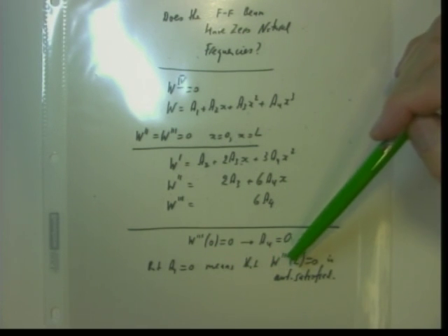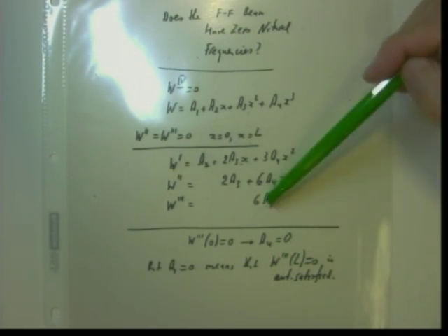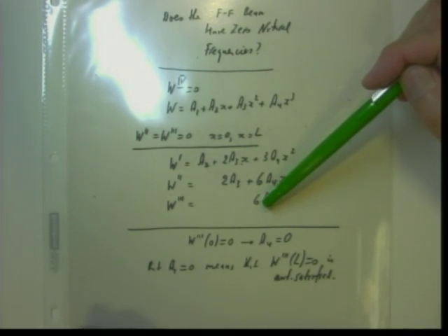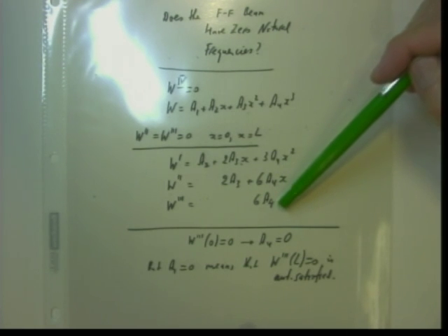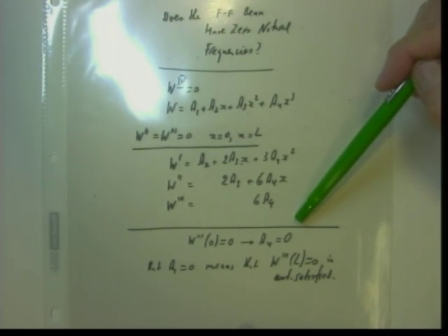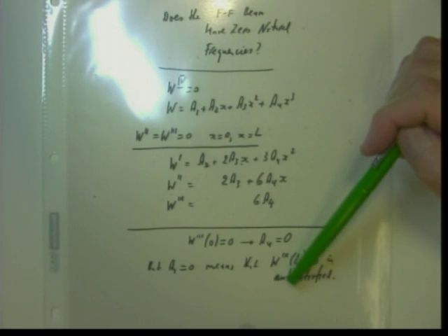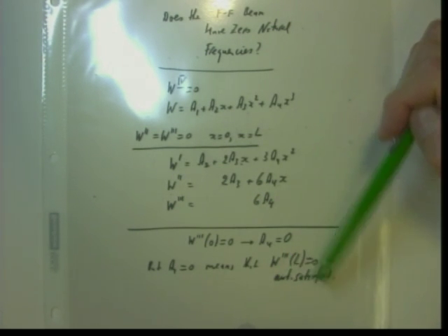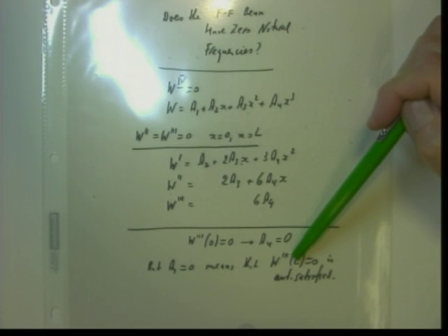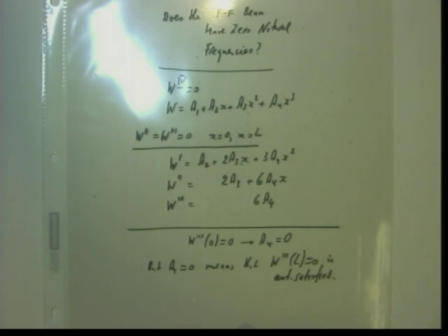That means that third derivative at L is also 0, because if this term is 0, then third derivative is 0 everywhere, for every x, because there is no x here. So therefore, we automatically satisfy the other condition also, third derivative at L. So then, because a4 equals 0, we are left only with 3 constants.